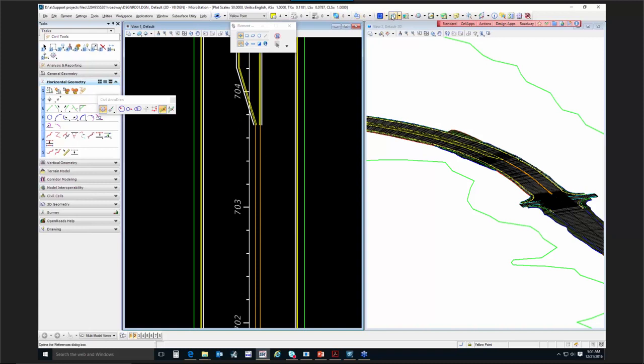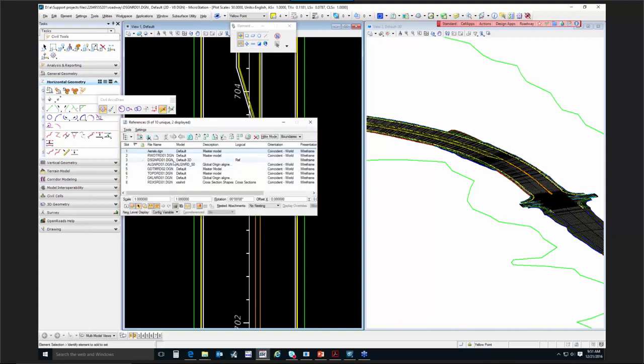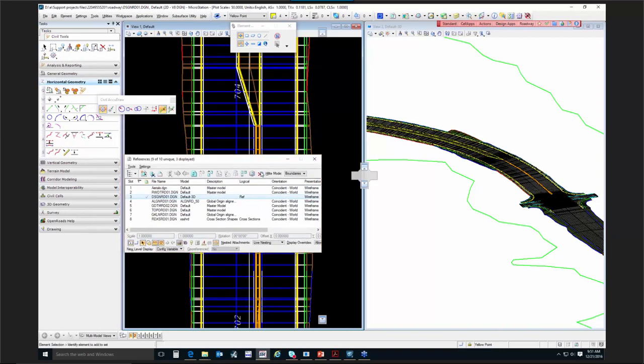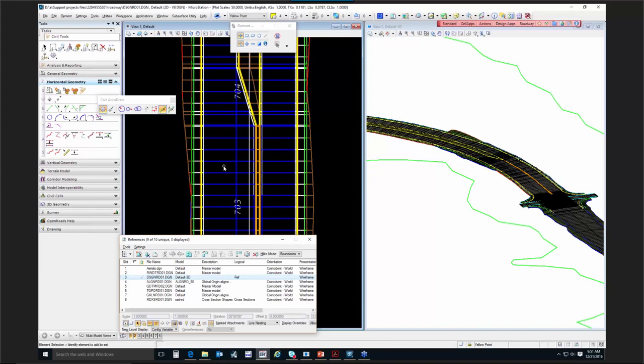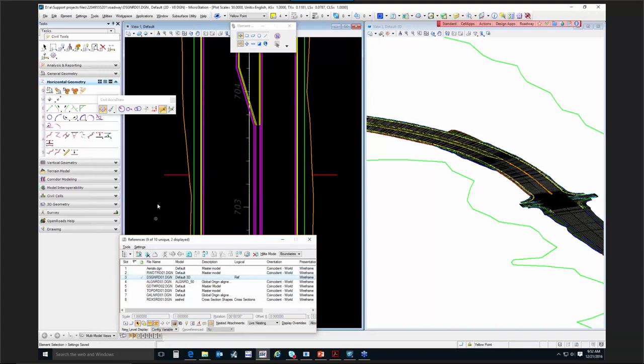Well, one way that you can do it is by going to the reference files. There's always a 3D reference file that you can turn on, and it's going to show underneath there. However, it's kind of hard to differentiate where the model lines are because it's kind of the same color. Even if you use F5, which dims it out, you might see them, you might not catch them. So one of the things that you can do is enable the features of the 3D line work to actually draw back to the plan work. And that's something that's done in the Project Explorer.